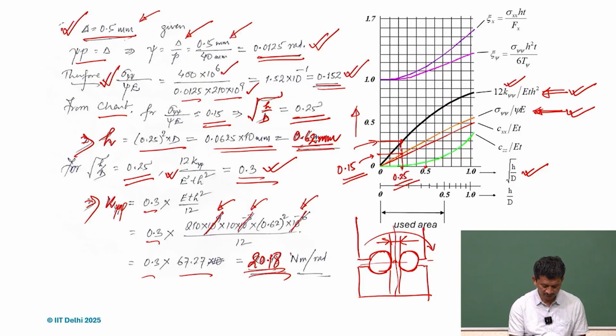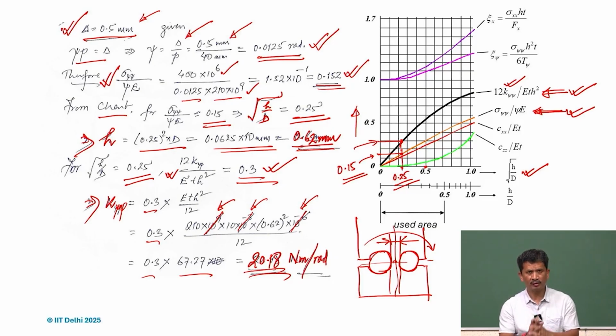Be aware of the unit for the hinge, so Newton meter per radian. It's an SI unit, and we should always be aware of the units as an engineer, because if we are not working with consistent units, we can have a serious problem.